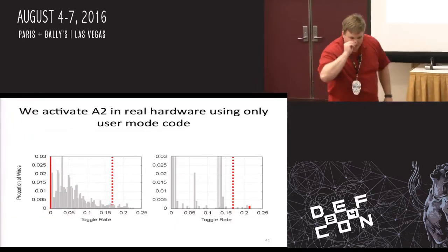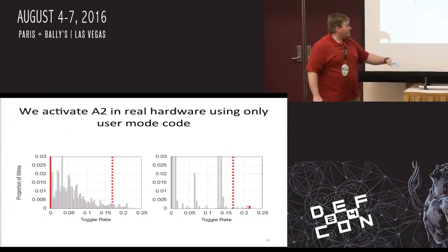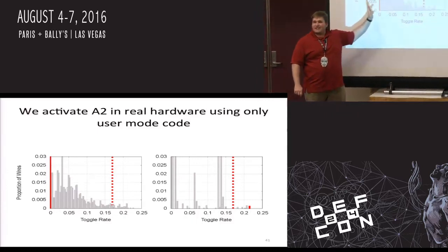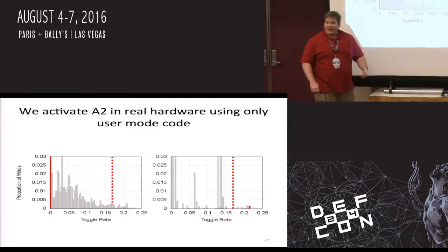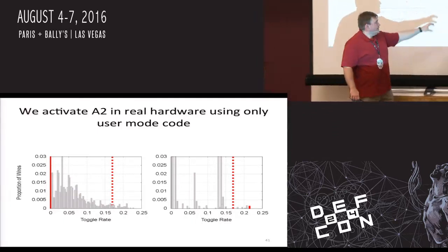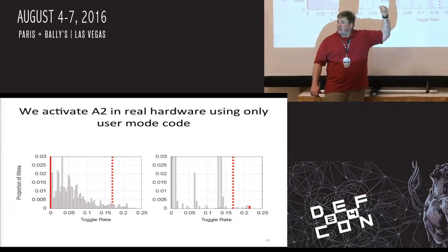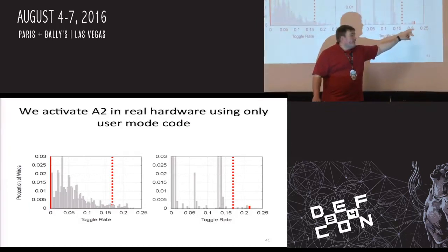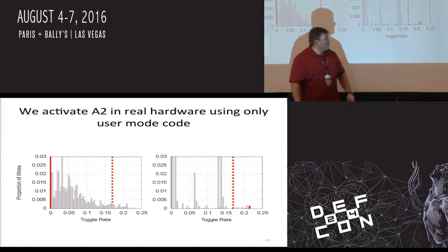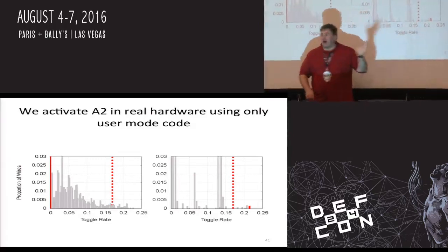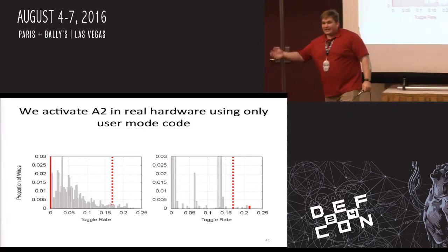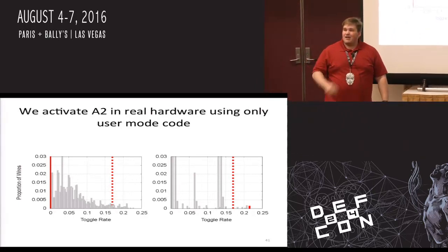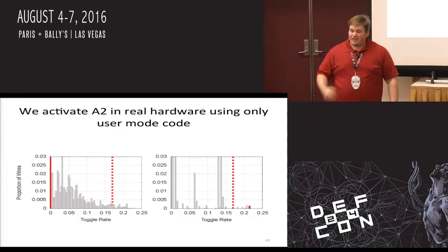Well, the next question is, we see here from the snapshot of that animation that even the benchmark that gets the closest doesn't come close to activating the attack. But can you activate it as an attacker? This snapshot is running that division by 0 code that I showed earlier, user mode code, and the solid red line is right here. These are all division by 0 and sign division related signals, and you can see it's well past that bar. So defenders can't trigger our attack without knowing exact specifics about it, but we can load user mode code that can trigger it ourselves.